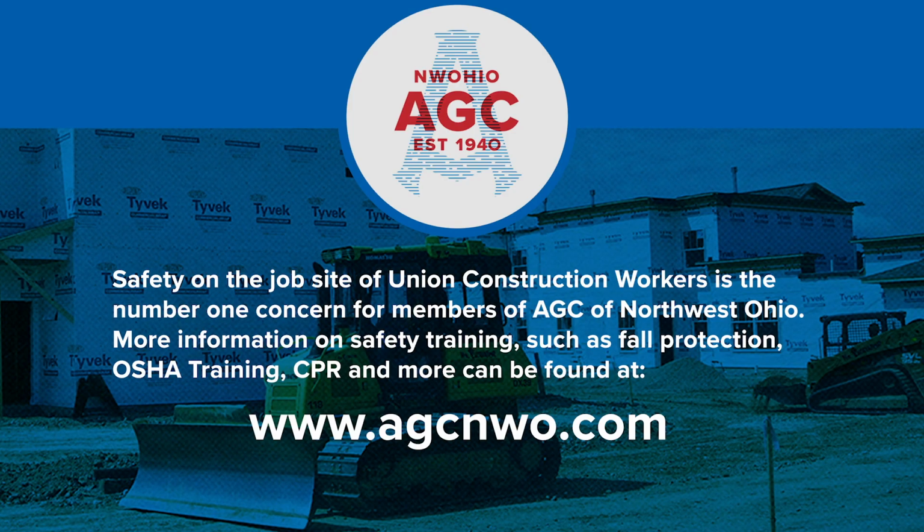The duty to have fall protection starts at 6 feet. When our feet are 6 feet above the lower level, or we are working above dangerous equipment, we must have fall protection. We also look at fall protection, scaffolding, ladders, stairways, steel erection, transmission towers, and other subparts in the OSHA standard. But please remember, Subpart M is where we start when it comes to fall protection. 6 feet is our trigger point in the construction industry, our duty to have fall protection.